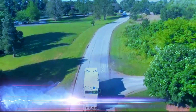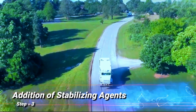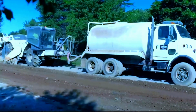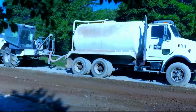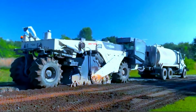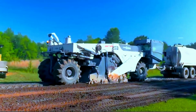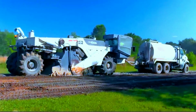Step 3. Addition of 2 to 4% of stabilizing agents. Depending on the project requirements, a stabilizing agent is spread evenly over the pulverized material. For mechanical stabilization, additional aggregates may be added. For bituminous stabilization, asphalt emulsion or foamed asphalt is mixed in. For chemical stabilization, cement, lime, or fly ash is blended with the material. A second pass of the reclaimer machine ensures a thorough mix of the stabilizer with the pulverized material.